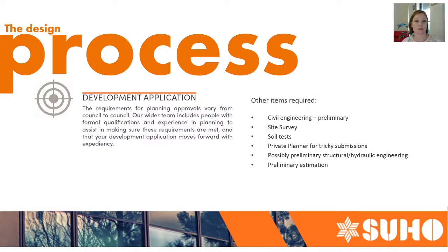So part of that is the civil engineering. They're wanting to really understand how stormwater is going to be delivered on site. Site survey, obviously, so that we can get the proper proportions with the neighbours. If you're asking for a survey, generally go a couple of metres beyond the boundaries so that we can make sure that we're not going to overshadow certain windows that are habitable on your neighbours. Soil tests.